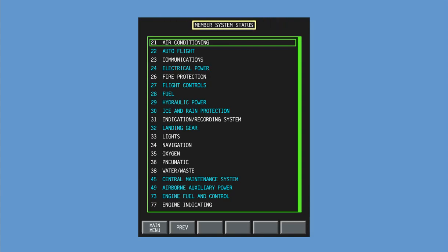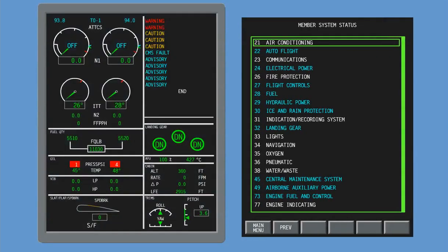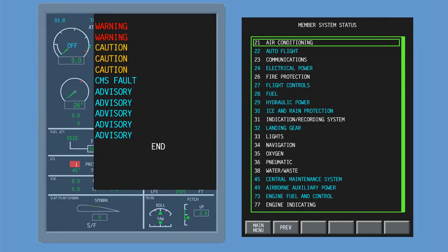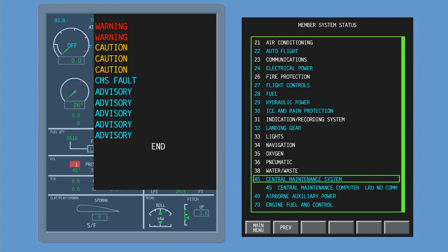Troubleshooting is started with the status page. This is because when the aircraft is on ground, many of the systems are switched off and they will be generating CAS and maintenance messages, but in fact, at this stage they do not represent failures. On the status page, you can identify which systems are operational and which are not. By looking at the non-operational pages, which are identified by cyan color, and cross-checking them with the active maintenance messages, it is possible to differentiate the messages caused by real failures from those caused by the current aircraft status on ground.